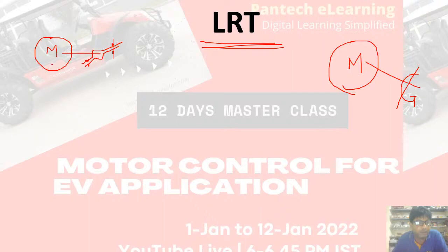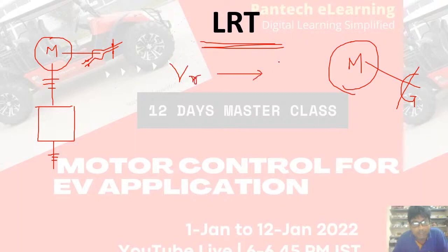The rotor shaft will be clamped, and this is your power supply. This will be given through an auto transformer. Now say the motor rated voltage is VR and the motor rated current is IR.